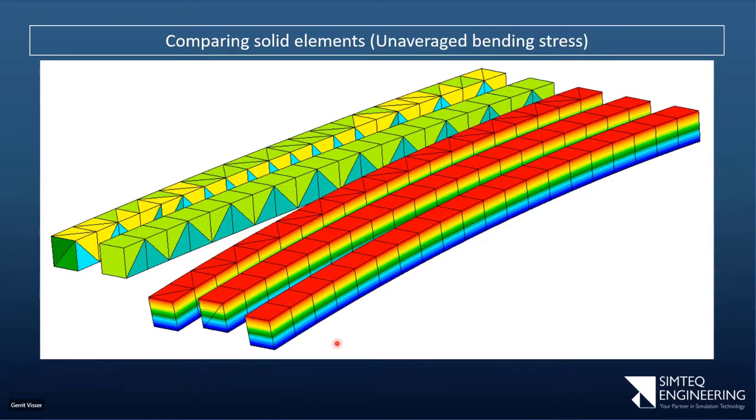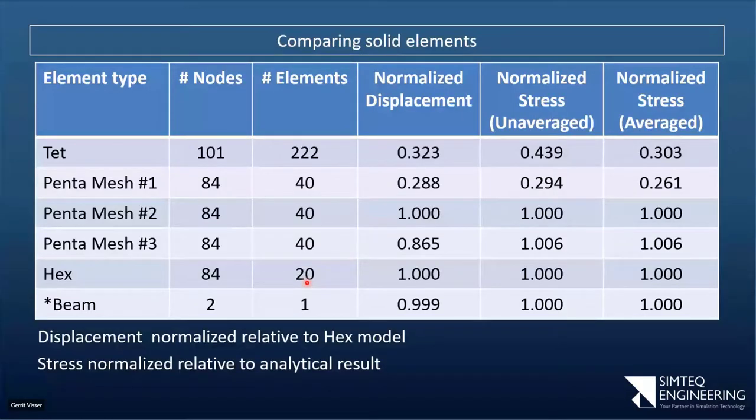Once you get to plasticity, it's more complex because then we have a pretty interesting stress state through the thickness. But for linear elastic stuff, depending on your element type, one element through thickness may be enough or is not even close to okay, depending on which element type we have. Okay, so some of the things that we'll also discuss a bit later on will be distortion of these different element types. Different element types handle things differently.